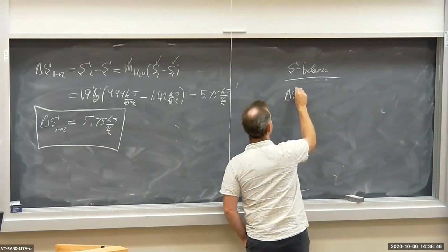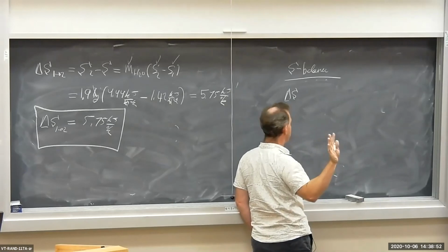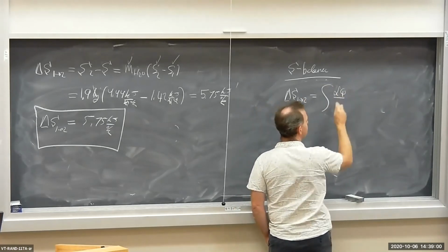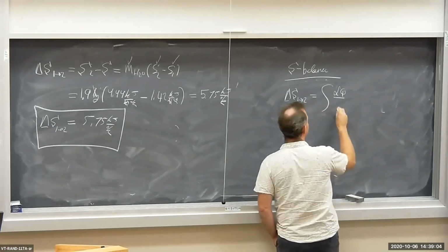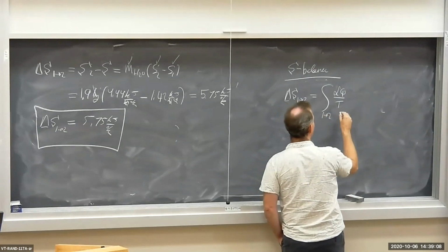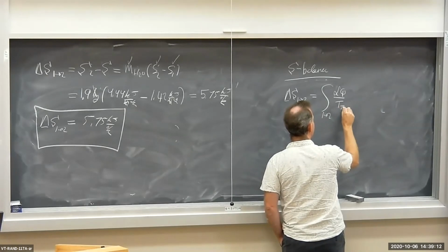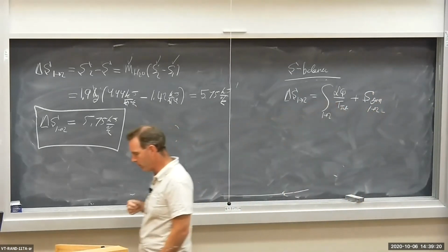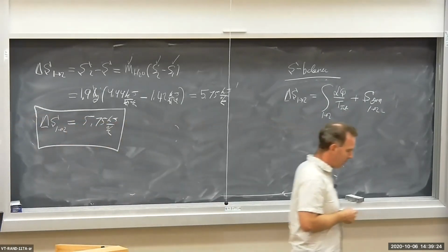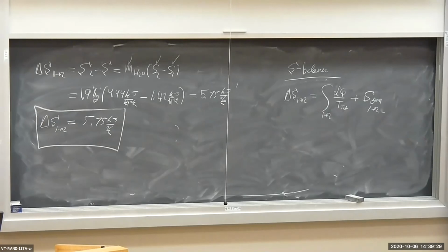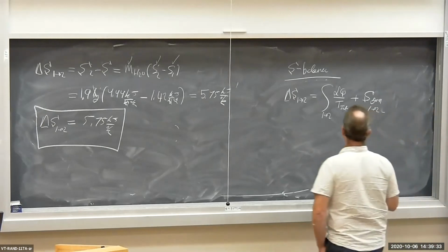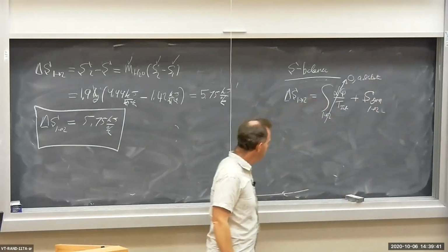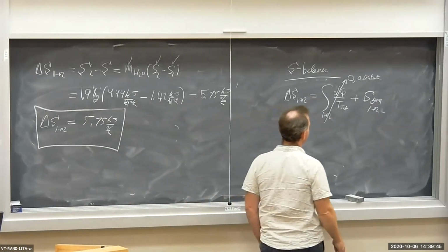What I've written is very similar to the open system entropy balance, so let's not get ahead of ourselves. Sorry, I'm thinking about the open system entropy balance. We're going to write the closed system entropy balance. So delta S from 1 to 2 is equal to the integral of del Q over T, where T is the interaction temperature, plus S generated from 1 to 2. That is the proper closed system entropy balance from the table that we saw last time. Again, this is an adiabatic process, so there's no heat transfer going on, so this term is equal to 0. And we simply get delta S from 1 to 2 for the water is equal to S gen.